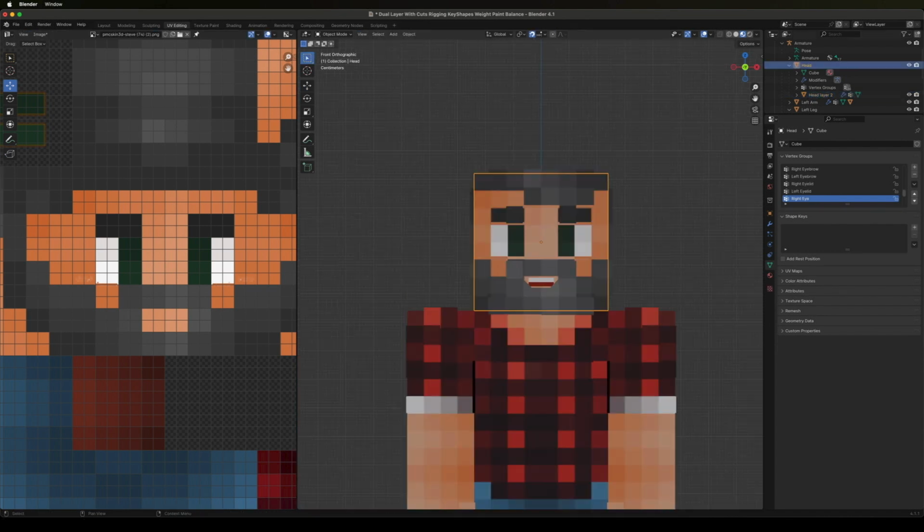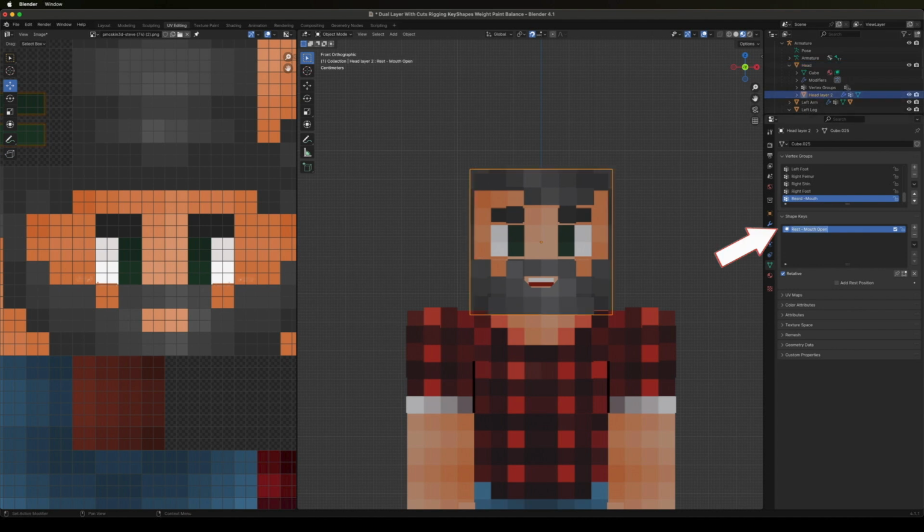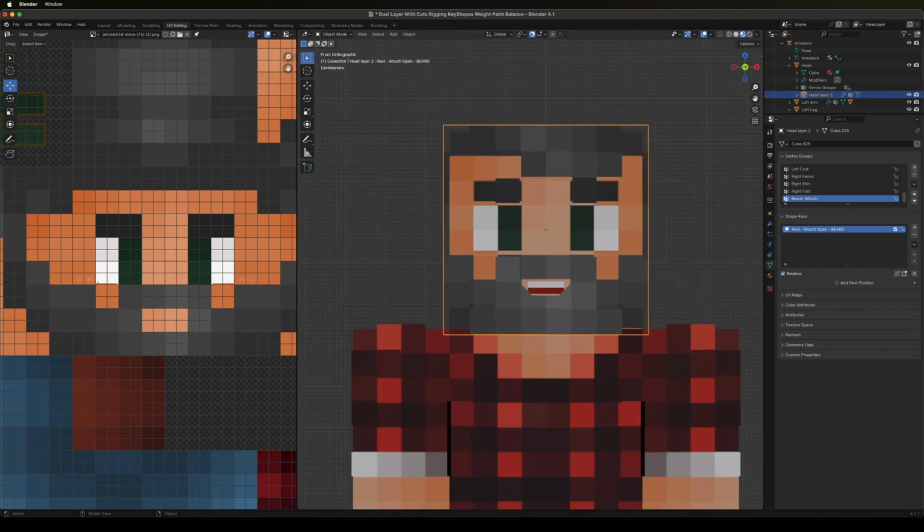We're now ready to actually deform the face. If you haven't done so already, assign grouped vertices to named vertex groups. We now add our first shape key without any deformation and label it Rest, and lock it. We need to be in object mode for this to happen. This will prevent any inadvertent deletion or adjustment of the features.